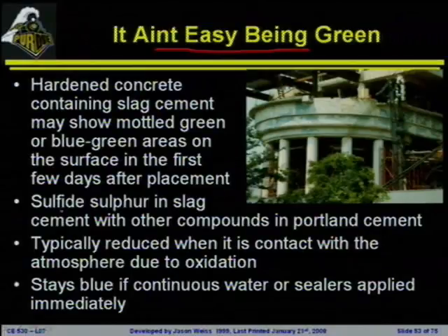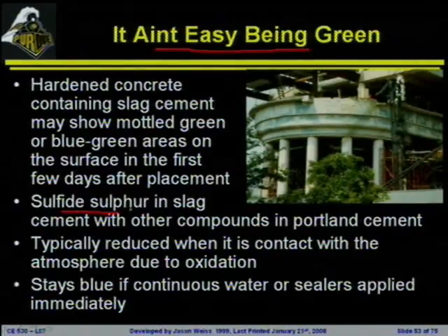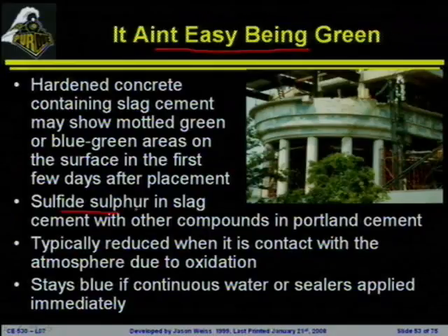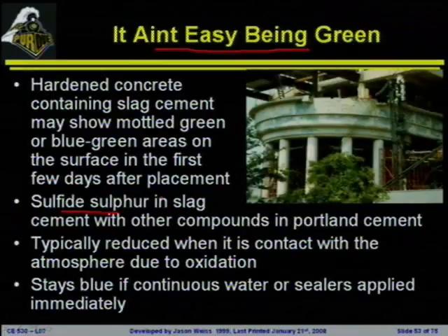It's actually the sulfide sulfur in the slag that's reacting. Typically when this touches the atmosphere, dries out a little bit, that color will go away. It will stay this funny bluish green color, however, if you seal it immediately. So what you typically want to do if you see this happening is allow it to get exposed to the atmosphere for just a little bit of time. That color will go away, and then start applying your sealer.